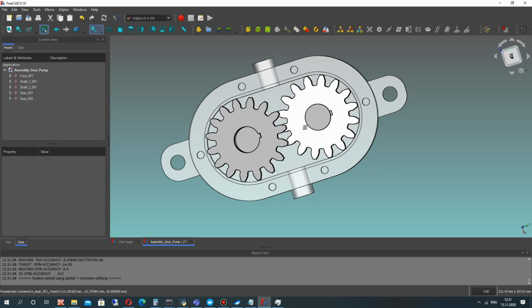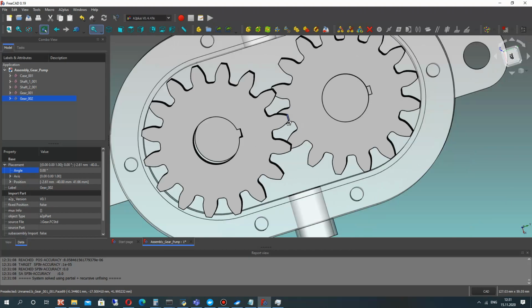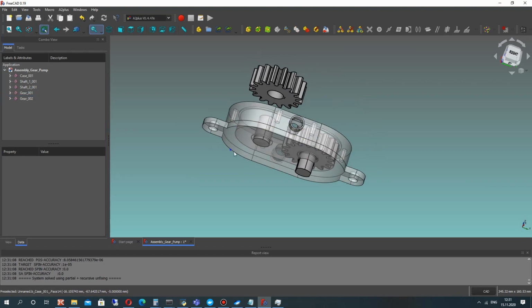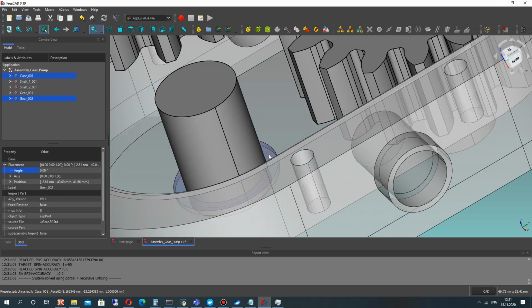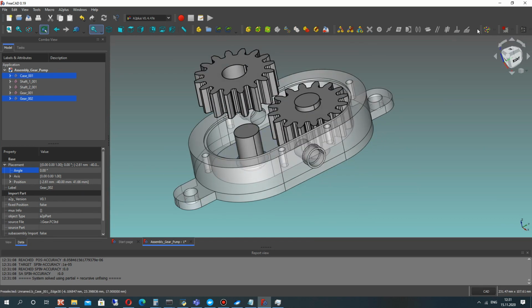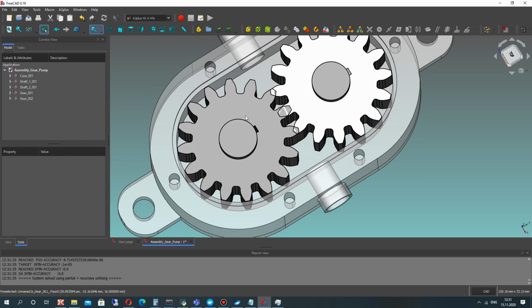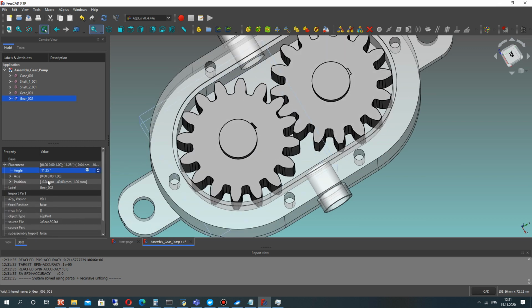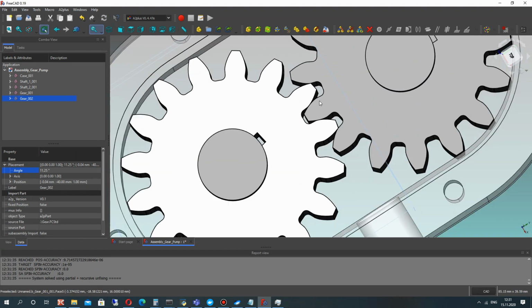And connect the two faces together, but we also have to set a constraint between our gears also. Okay, let's set the axial position of the gear, and we have these faces between geometry, and let's set some angle here.